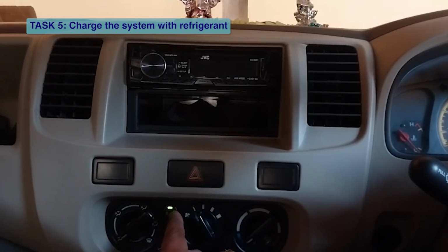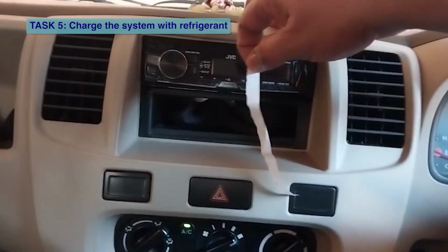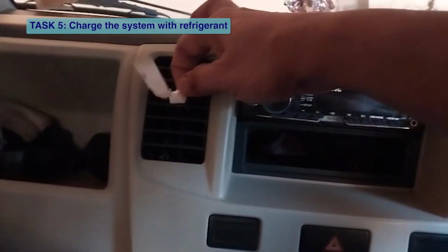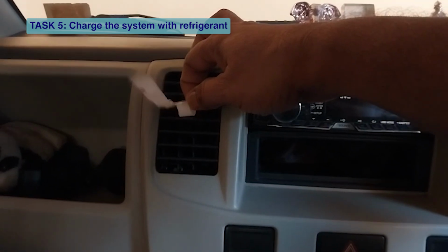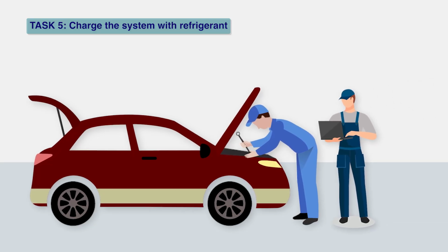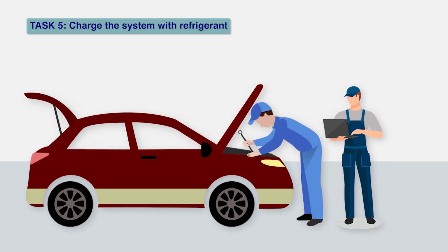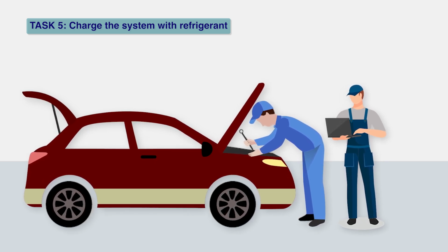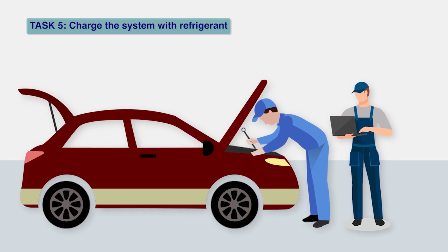After charging, test the system's functionality to ensure it is cooling properly and that there are no leaks. Record the amount of refrigerant added to the system and any other relevant data for future maintenance or troubleshooting purposes.